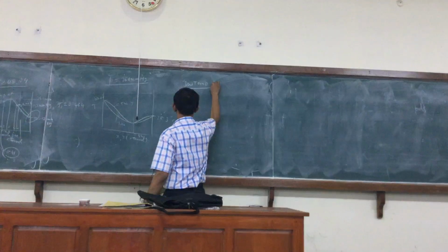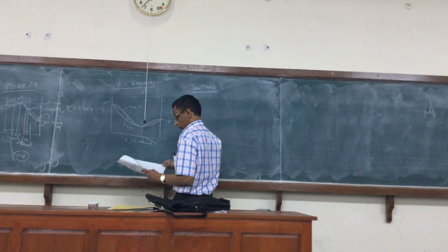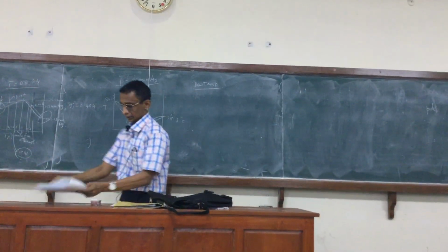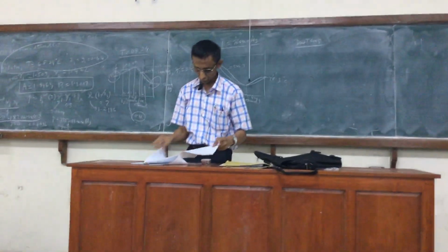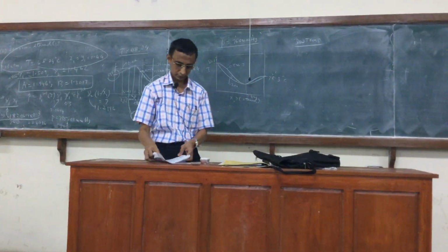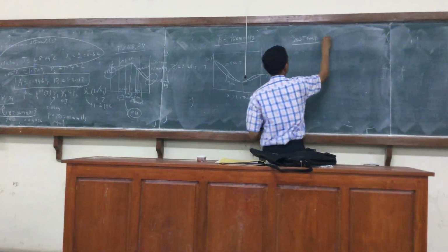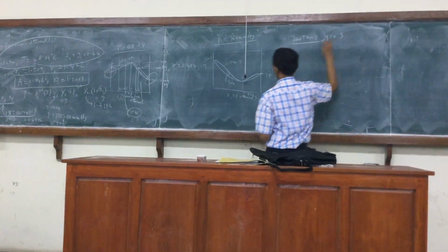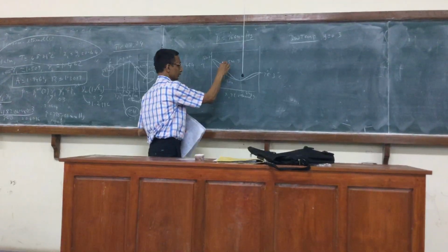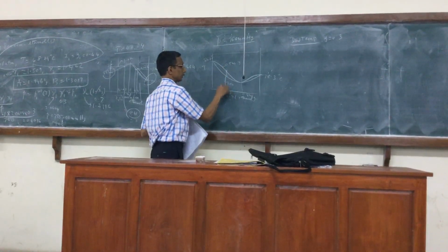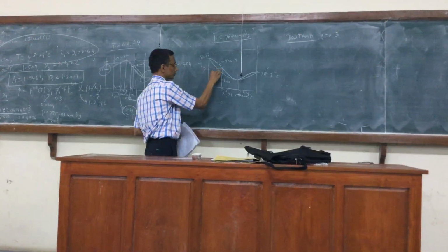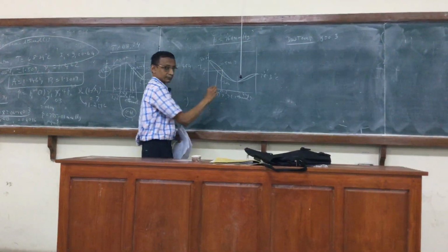Calculate. Just give you an outline. You can go ahead and do a few of these iterations yourself. So what I have here is to calculate the dew temperature at, let's say, y equal to 0.3. So I'm at this end and y equal to 0.3, and on this curve I have to mark 0.3. So this is the temperature I want. And I obviously want also the corresponding x.